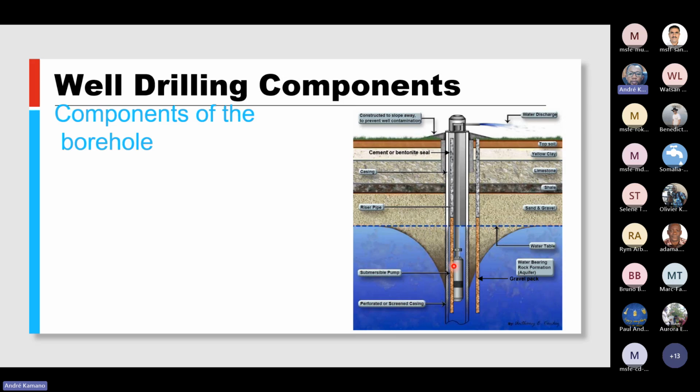Okay, the other point that we mentioned is actually the pump. But this one is not there during the drilling. It's after we have finished the development of the borehole, or the drilling, that we put it inside. So it will help us to take out the water. And you may know that this pump is linked to outside connections by the power cable, but also by the pipe, which can be PVC or sometimes galvanized. And the power cable is there to let our water go a bit up.